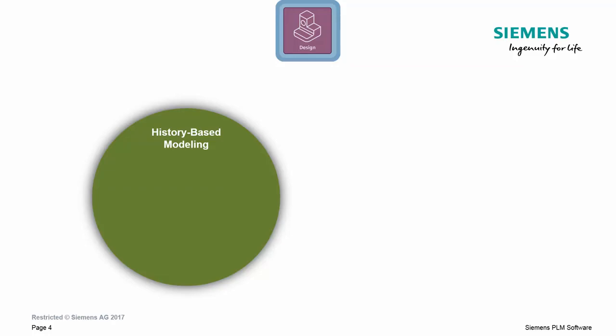Designers used collections of features such as extrusions, lofts, sweeps, revolutions, cuts, and holes to build digital models. Each new feature had to be built on top of the one created before it, utilizing the outcome of the previous in order to create the next. This process has been coined history-based modeling, or ordered modeling as referred to in Solid Edge. Solid Edge has supported ordered modeling methods for over 20 years with both its strengths and inherent challenges.